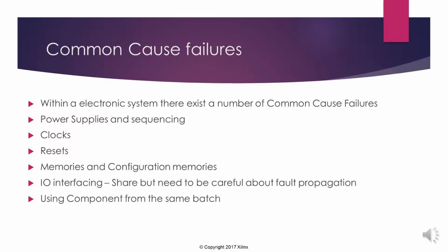And within electronic systems, there are numerous single points of failure. So obviously power supplies and sequencing: we can't power redundant modules off the same power supply, because if that power supply fails, it's a single point of failure. Same for clocks, resets, memories and configuration memories.